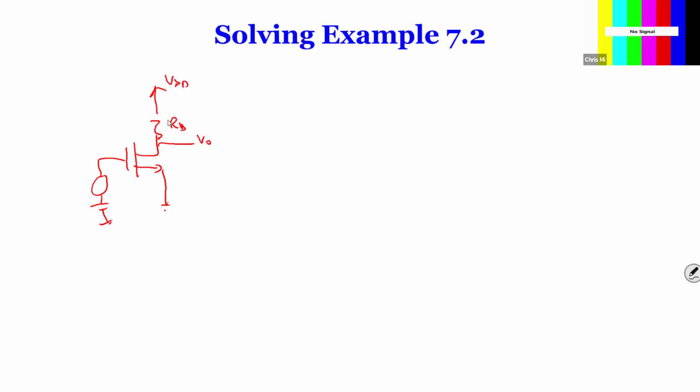And then here we have a circuit of... So for output range, for example, for the MOSFET, the minimum range is where the transistor goes out of saturation. How do you maintain the transistor in saturation? You have to maintain VDS larger than VOV, right? So that's your minimum.